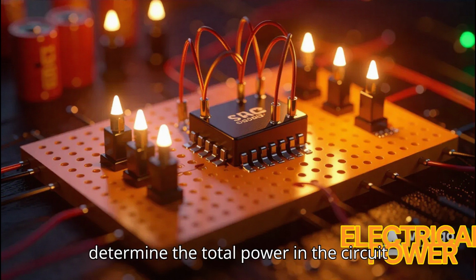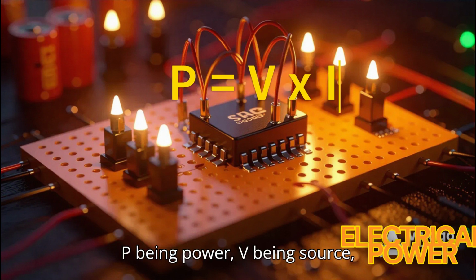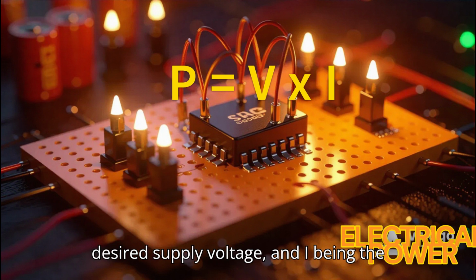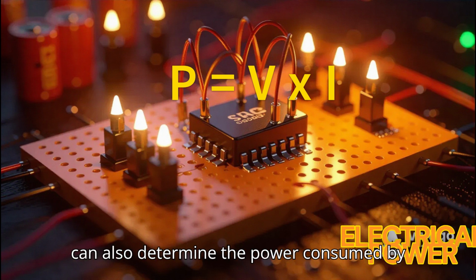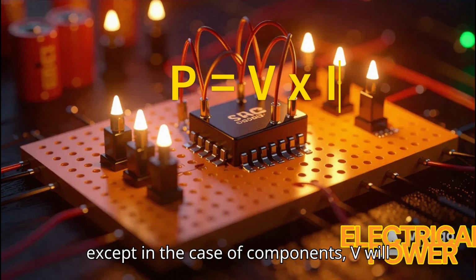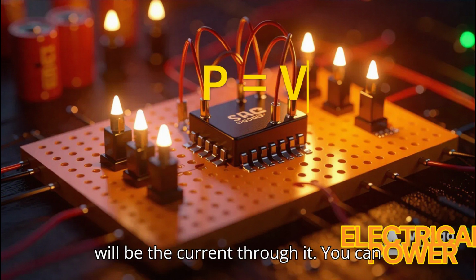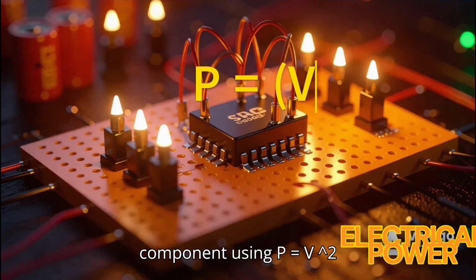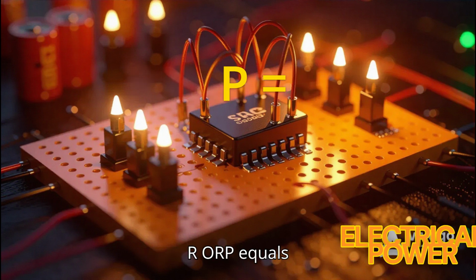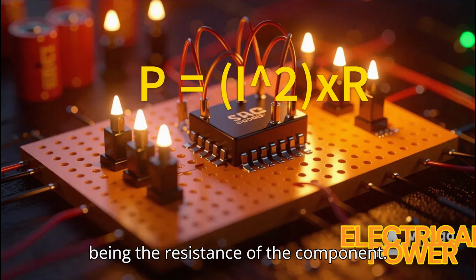You can determine the total power in the circuit using P equals V times I, P being power, V being the source supply voltage, and I being the total current through the circuit. You can also determine the power consumed by each component using the same formula, except in the case of components, V will be the voltage across the component, and I will be the current through it. You can also determine the power consumed by the component using P equals V squared over R, or P equals I squared times R, R being the resistance of the component.